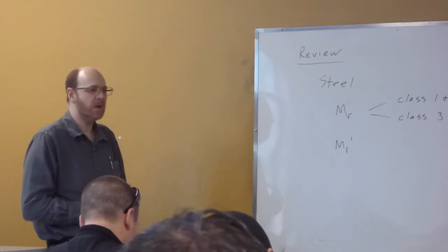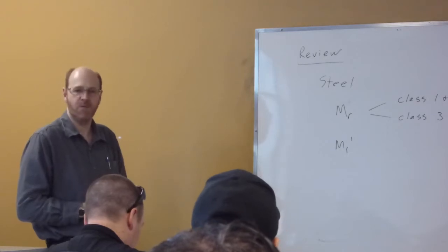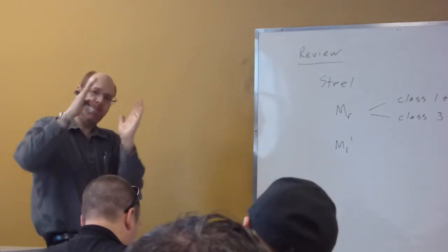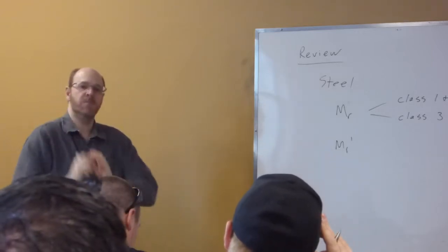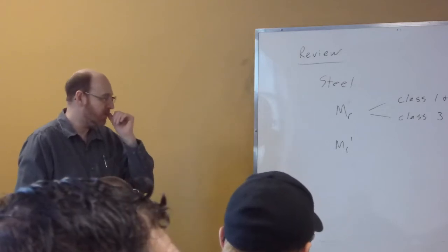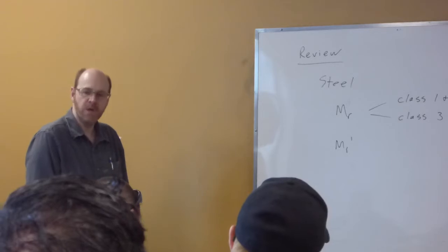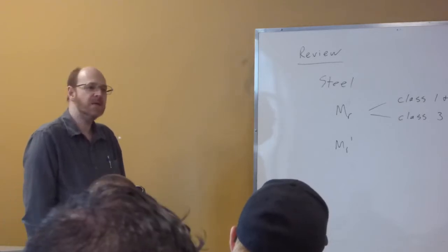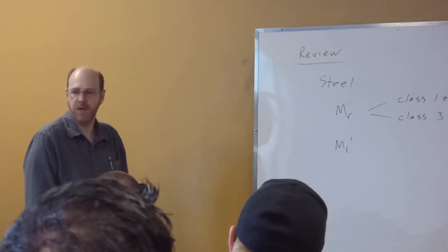Right? So here now is a reduction factor, and I won't write out the formula for this because it's a fairly long, complex formula. There's a bending component, there's a twisting, and then there's a distortion component as well. So the formula is quite complex, and it takes a number of factors into account. What we have to recognize is if I have a scenario for which there is unsupported bending, I need to make sure that my moment resistance is reduced based on that unsupported length.